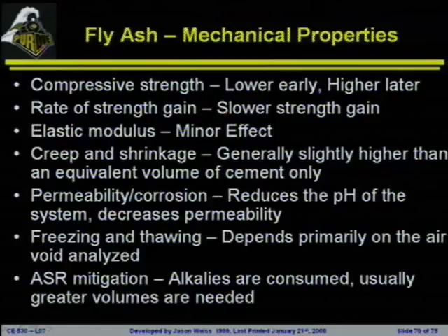Mechanical properties, there really aren't a whole lot of big differences in the mechanical properties. They will tend to gain strength a little bit more slowly. Generally, elastic modulus, similar. Strength is going to be similar. Creep and shrinkage are going to be similar. They will improve a little bit of the long-term durability by reducing the pH, and they will tend to reduce some of the ASR problems because they will take some of the alkalis out of the system.